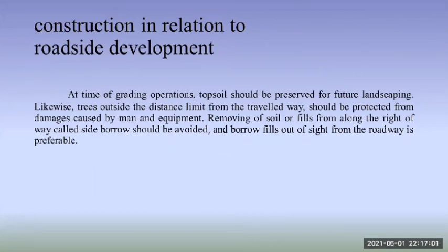Construction in relation to roadside development. At the time of grading operations, topsoil should be preserved for future landscaping. Likewise, trees outside the distance limit from the traveled way should be protected from damages caused by man and equipment. Removing of soil or fields from along the right of way, called side borrow, should be avoided, and borrow fields out of sight from the roadway are preferable.